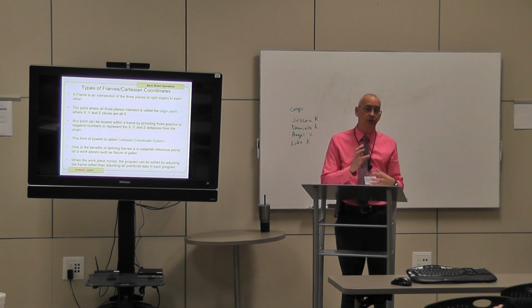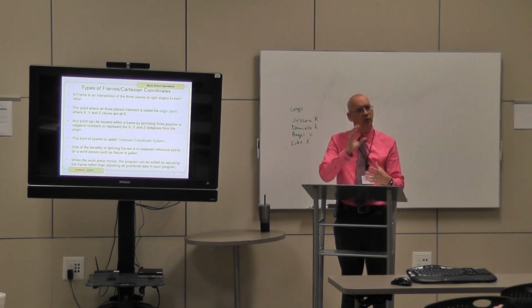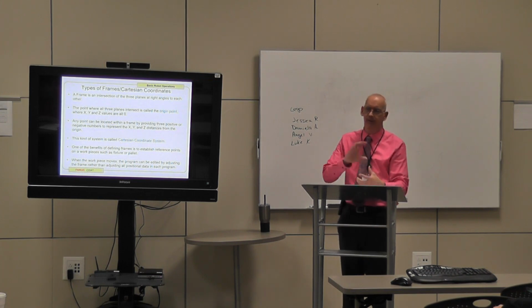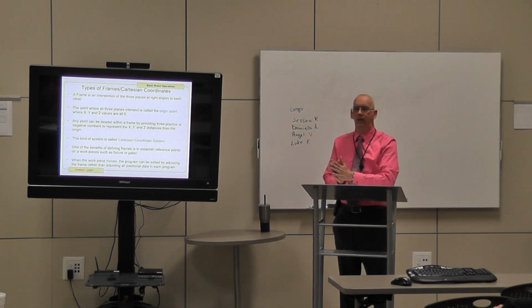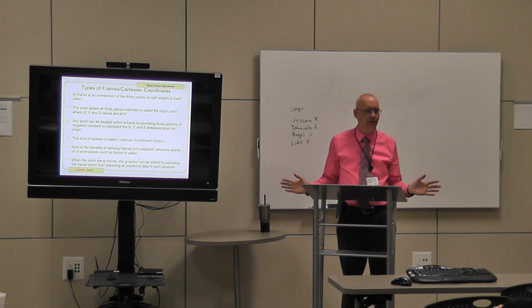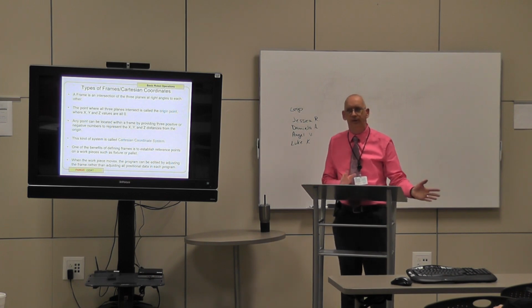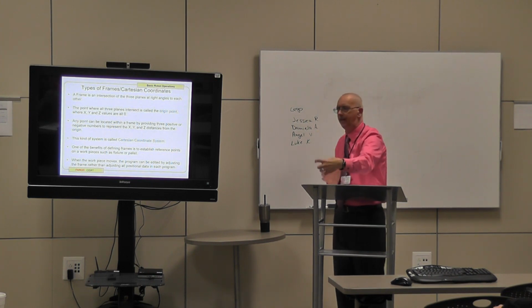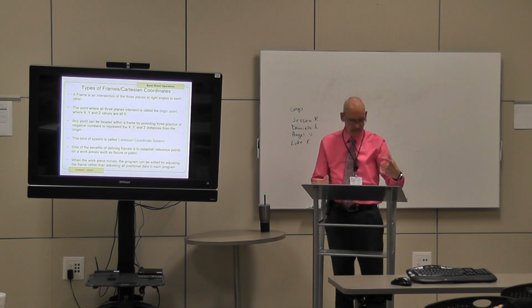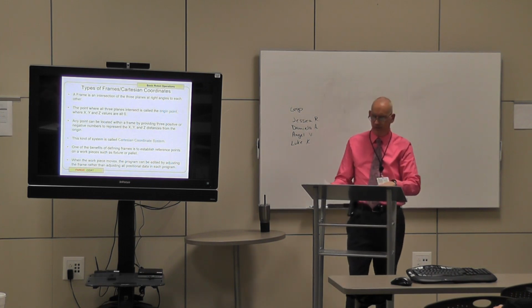When you have a certain tool, you have to define that tool frame, and you also have to define that work area specific to what you want to do. Again, world frame has a different location of origin, where your user frame would have an origin point that you define. So don't lose count of that as we move forward.